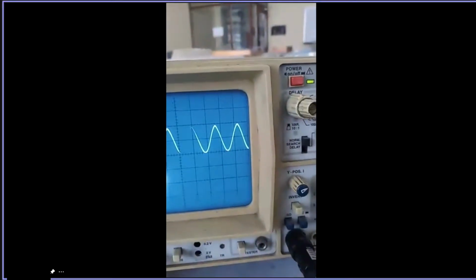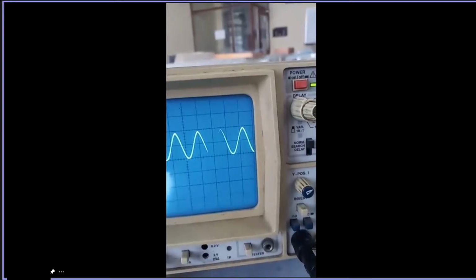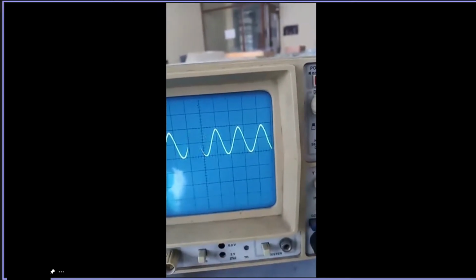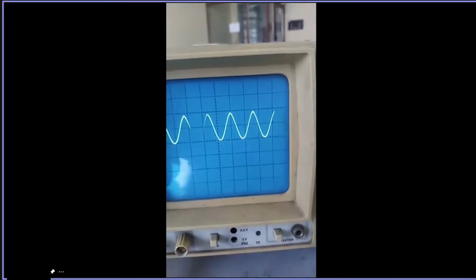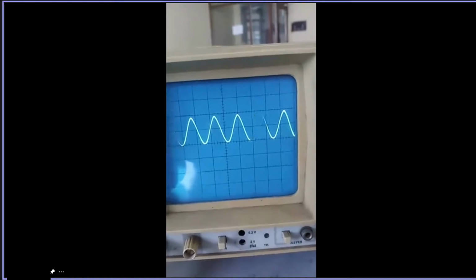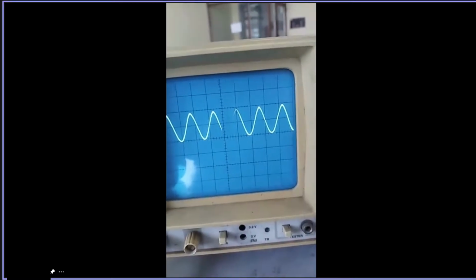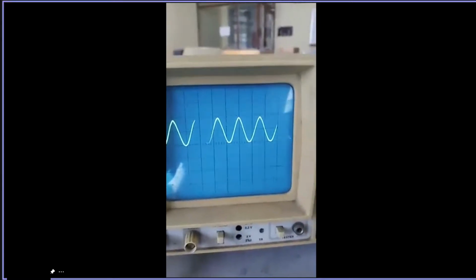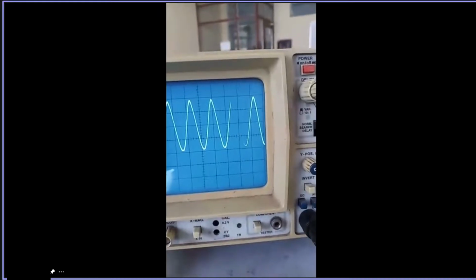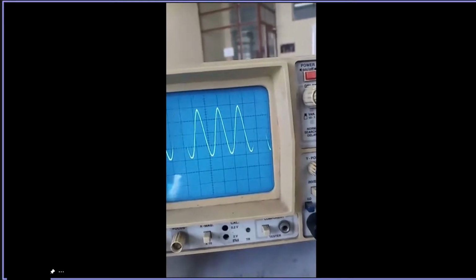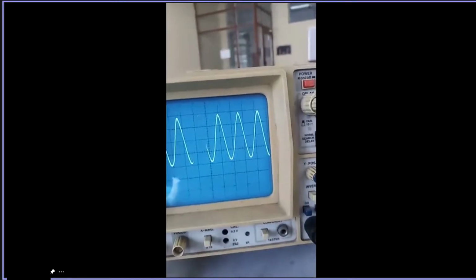So this is, you can see, yes, 6 numbers. Okay, so this is the output of the second order filter. Still, you can see the same voltage because we have not changed the voltage, only the frequency has changed, right? So we still have 4 volt output. And now if you see at fourth order, we still have the 8 volt. Only there is a variation in the time period because we have changed the input.